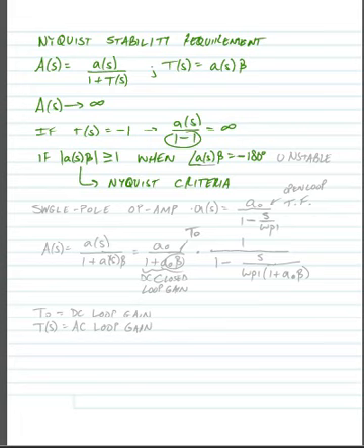And essentially what it's saying is that since we're already configuring the operational amplifier in negative feedback, we already have 180 degrees. If we get an additional 180 degrees of phase shift from our loop gain, the feedback to the input of the amplifier would become positive, and we would have a positive feedback system, and we know that positive feedback systems are unstable.